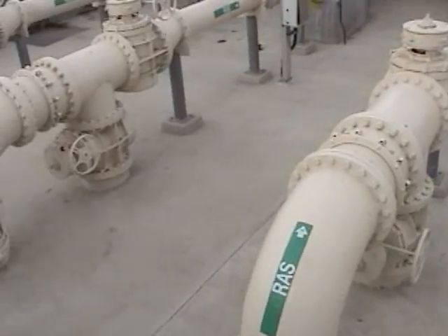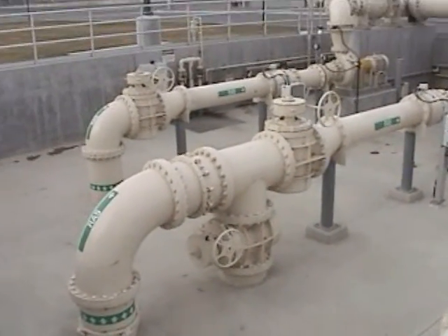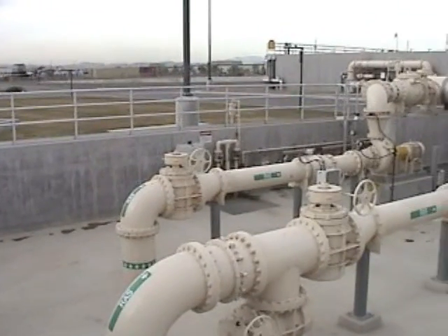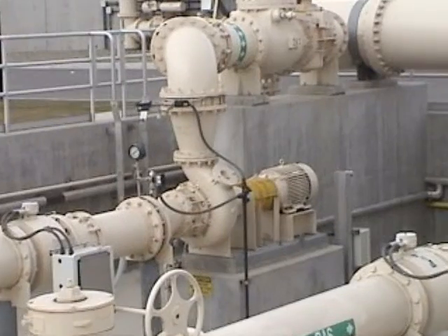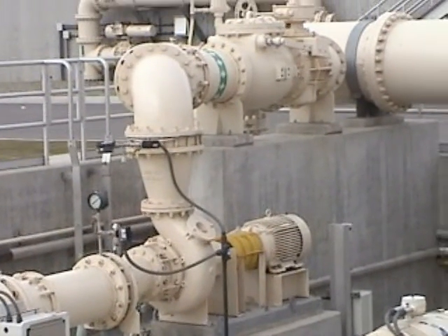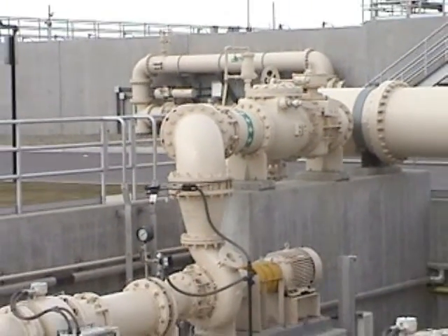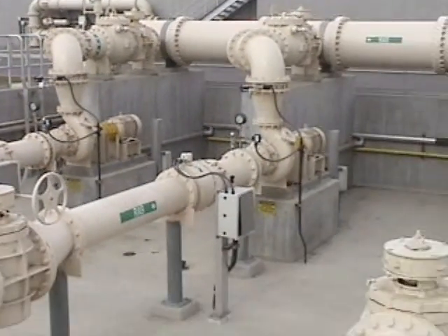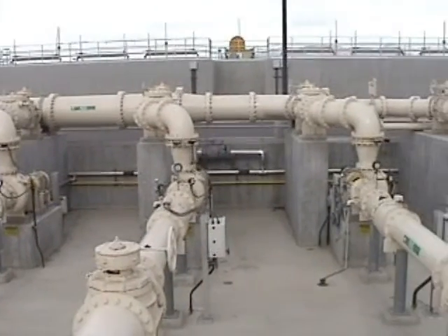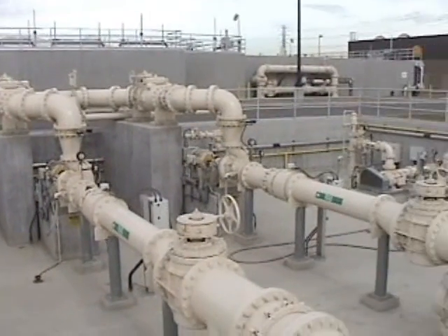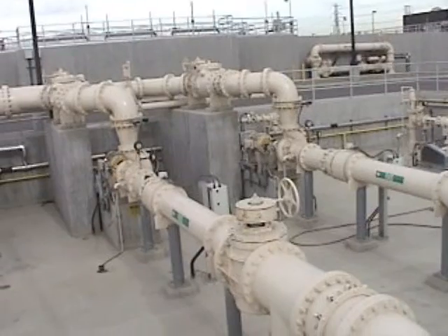And you can put RAS pump number 10 online. We usually don't run RAS pump 10, only on occasion just to exercise it, because we don't want it to sit there and freeze up or something like that. But it's really important to take good care of RAS pump number 10, because it's the only pump in the RAS station which can replace any of the others, because of the way the piping is.